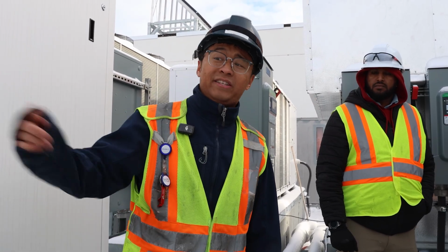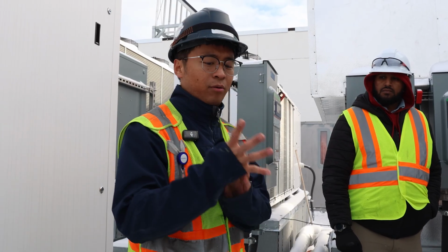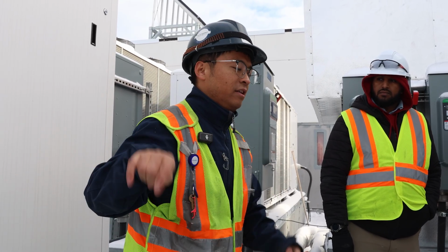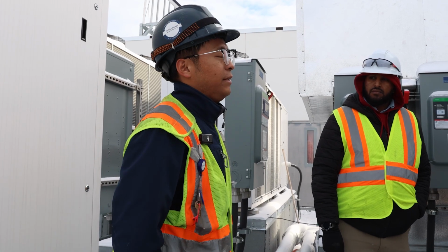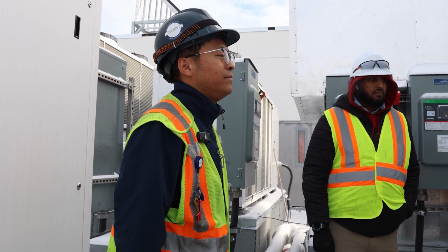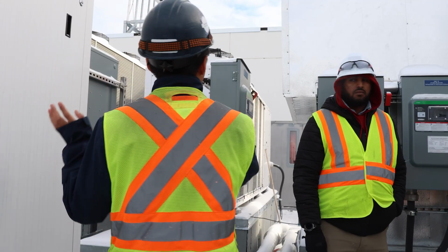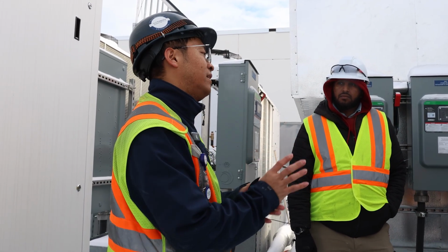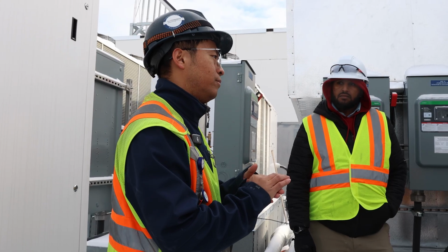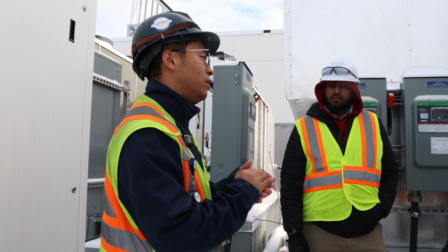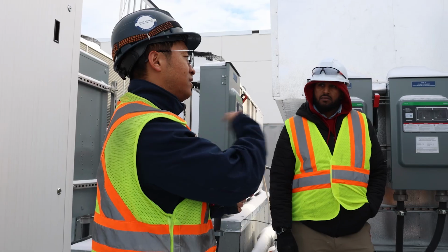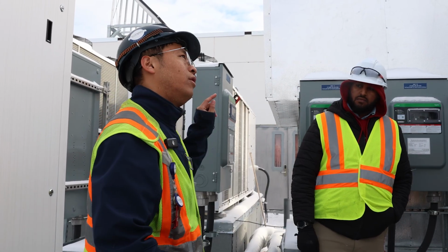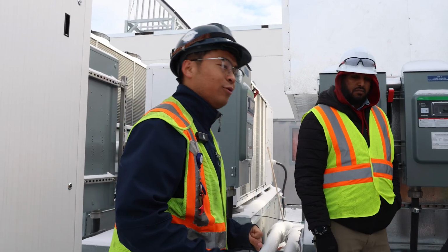Right now, it's in the winter. The air source heat pumps 1A, 1B, 1C, 1D are in heating mode, and they are in the building primary loop. So right now, they supply the heat to storage tank 1 and storage tank 2. Then there is a pump that transfers the heat to the heat exchanger. Once we look at the graphic, it will be much easier to understand.